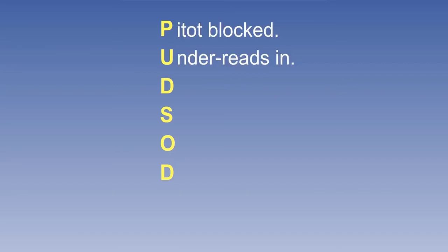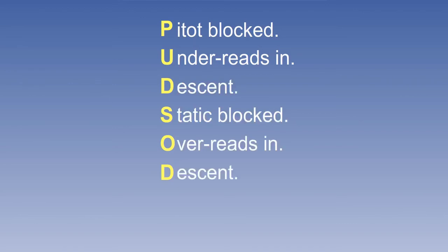In examinations, when you have to recall the effect of a blocked pitot or static probe quickly, without working it out from first principles, a useful aide-memoire is PUDSOD, which stands for pitot blocked, underreads in descent, static blocked, overreads in descent. Remember this mnemonic because these types of questions are very common.